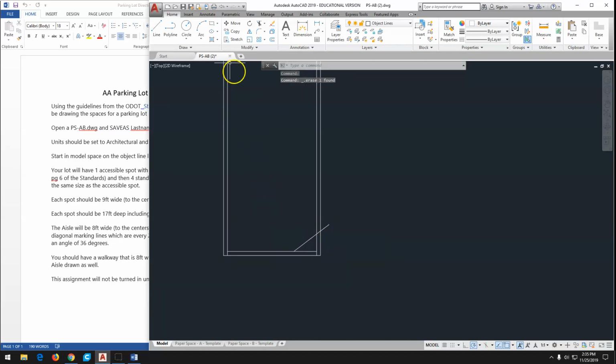Now I'm going to go ahead and offset 4 inches again, this line above, and I can use the extend command, and I'm hitting enter to select all, and you see I can extend that down to the end there. Then I can use the trim command and hit enter to select all and trim out the portions that go through here.